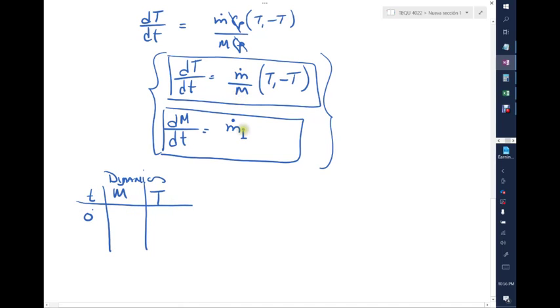Let's say that we are working with a very small tank or reactor, something like a lab experiment, and let's say that the mass is about 800 grams, and that the temperature is kind of hot water, about 80 degrees C. And those are the initial conditions. If I keep working on these, like 0, 10, let's say that the delta T for my Euler method will be about 10 seconds, then we can integrate both of these equations using the Euler method.